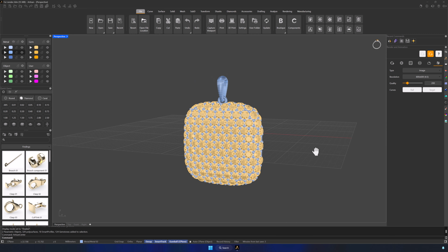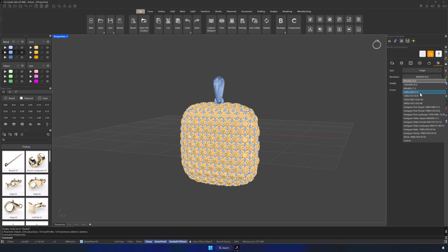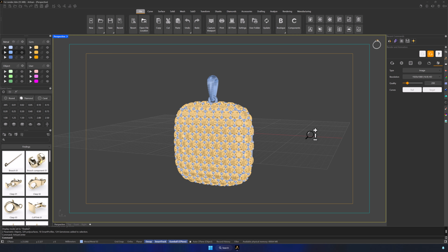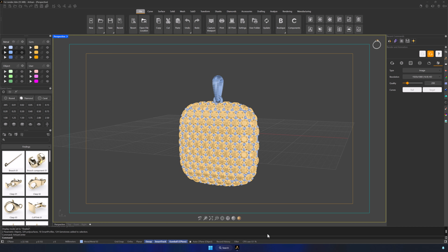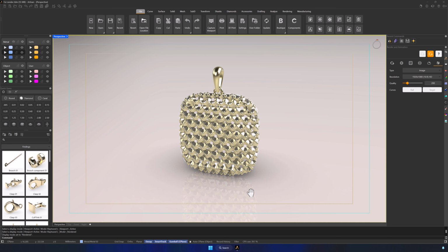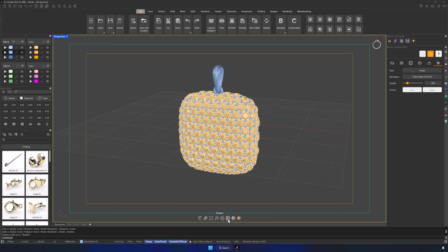You can select a resolution to view the guides. Everything within the lines will be rendered. Before rendering, switch back to rendered view and adjust the viewport position so that the background fits within the frame. Now, in the Render and Animation panel, change the render type to Turntable and under Video choose Custom.